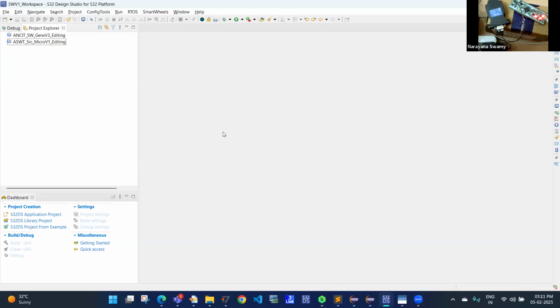In a quick way, if I have to explain, normally if we sell this hardware to anybody, the first thing you are going to ask me is, where is the schematic? Which are the pins? Which is the digital input? Which is the digital output? How is it connected? Is it internally pulled up, pulled down? You are going to ask hundreds of these questions. And even if I give you this board today, just to take a digital input and drive an LED, assume that I want to read a digital pin. Say this is the switch. If I press this switch, an LED has to be switched on.